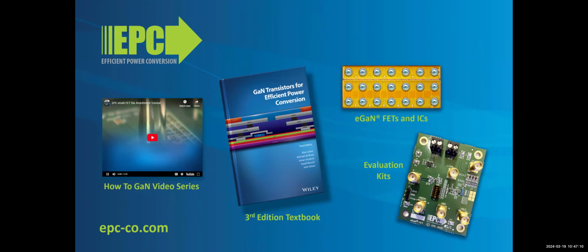Thank you, Marco. Another question is, when it comes to industrial motor drive applications, where the drive is inside a cabinet and connected to the motor through a probably long cable, there are additional things to think about. An increase of switching frequency will cause additional cable losses, and the high switching slope will cause significant overvoltages at the motor terminal, causing additional losses too. Do you have any experience up to which cable length the GaN application, 100 kilohertz versus 10 kilohertz, is more efficient than silicon? Drive with about 60 volts DC and several hundreds of watts.